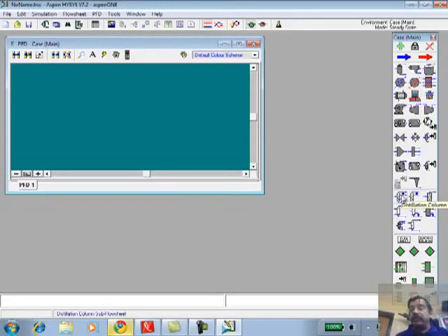And there are some powerful tools for distillation columns. We can simulate the entire column of 50 trays or whatever and predict what is going to be its output compositions and flow rates. The models behind that are really very sophisticated. But they are all algebraic equations, nonlinear algebraic equations, because this is a steady state process simulator. Now, there is a dynamic component that we will see later on, but we're going to see the steady state.